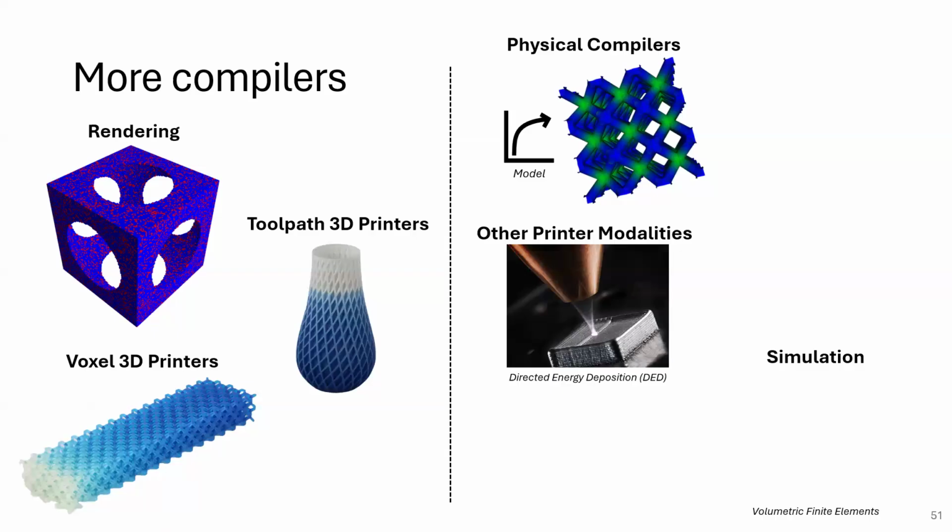So this is another reason we're interested in applying simulation so deeply into the 3D printing process. While we're printing, to maintain quality, we need to make sure that we don't have too much heat concentrating in specific parts that might result in cracking or unintentional porosity, especially as we move toward these multi-material DED parts where we might have materials that behave differently at different temperatures.